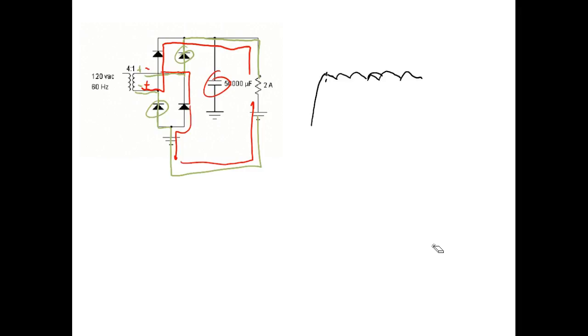And this is what we call unregulated DC, because I showed y'all what happened. When I put a bigger current load on there, the ripple got bigger. And if the ripple gets bigger, it means the output voltage drops. So we had the multimeter on there, and when I put that other resistor in parallel, which required more current, we actually saw the digital multimeter read less, and of course that was because the ripple got bigger, right? You understand that? So we call this unregulated, which means it's going to vary with loads. Also, it's going to vary with the input.